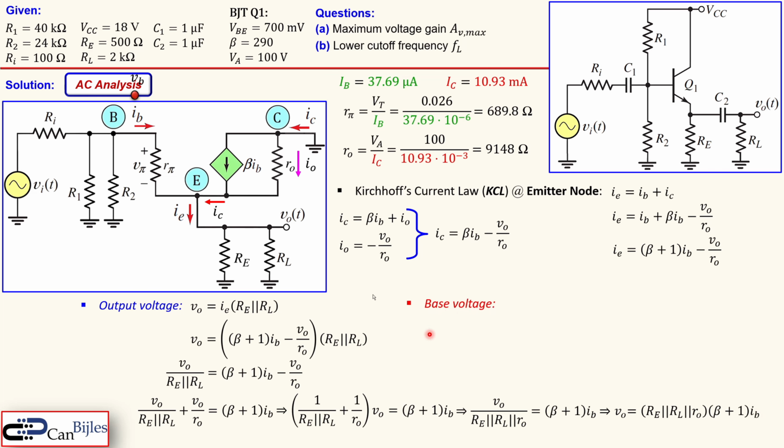Well, the base voltage is this node, so VB, that is the voltage across R pi, plus the voltage VO. And VO is shown here, so we can take this. Now we see here again an expression with R pi, beta, and also in terms of just IB, which is our base current AC.